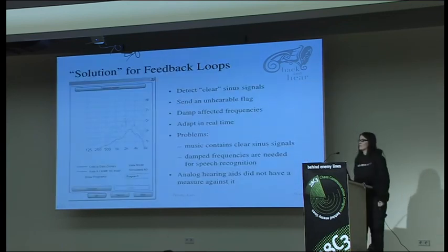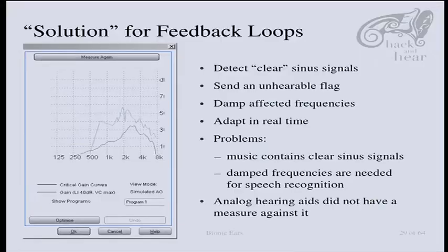And what the hearing aids do is they try to detect feedback loops. So they look for clear sine signals, and when they detect one, they send an unhearable flag saying they detected one, and then the affected frequencies get damped until it doesn't squeak anymore. They can adapt in real time, so it actually works really fast, but it's still hearable.